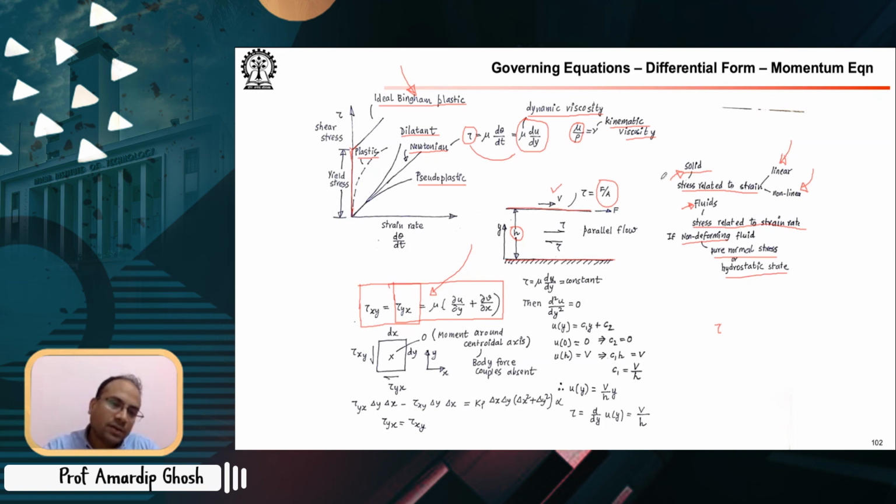Now, when you start pulling it, I think some transients will be there, but eventually, what will happen is you will end up with a situation where, if you impose the condition that the shear stress is constant along this height, what will happen? Part of the reason is, since the pressure outside these parallel plates is the same, this is a flow driven by shear forces only.